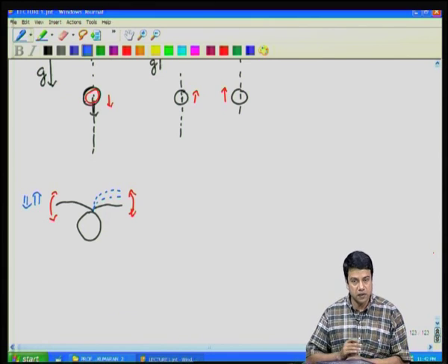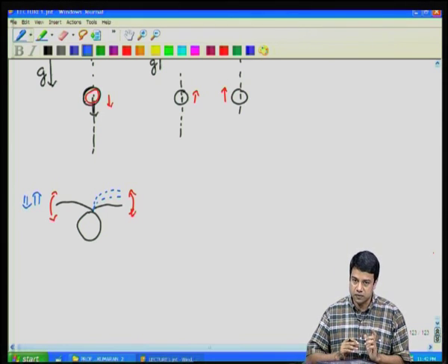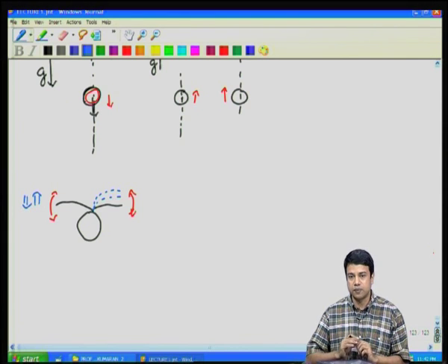Therefore, you cannot use periodic motion for microorganisms to move in the limit of very low Reynolds numbers. They have to use something that is non-periodic, a non-reciprocal motion for example, in order to move in one particular direction. This is very different from what you are used to at high Reynolds numbers. At high Reynolds numbers, because of the nonlinear term, there is no reversibility, and it is not quasi static either, and because of that a periodic motion could generate a thrust in one particular direction.